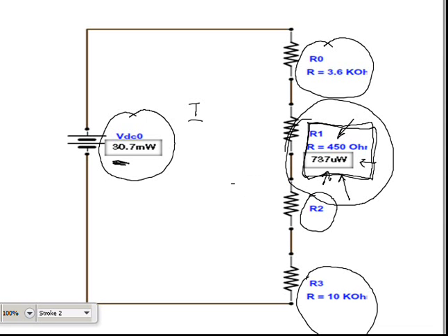Current. So, how do I get current out of resistance and power? Well, once again, mixing Ohm's law with the power equation, we know that current equals the square root of power over resistance. So that is going to give me the current for the entire circuit by knowing the power and the resistance of the single resistor.